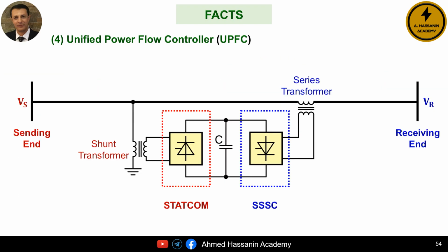The last thing we need to know is that UPFC devices consist of electronic circuits made up of a group of gate turn-off, GTO, thyristors, as well as a control unit whose function is to control the amount of active power that is required to flow through the transmission lines.